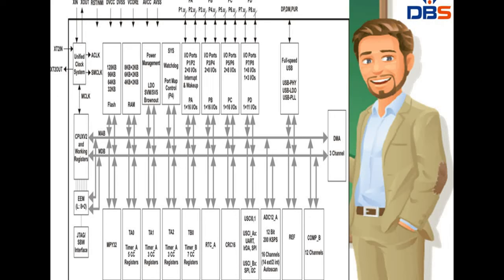Port 1 and port 2 have interrupt capability. Each interrupt IO line can be individually enabled or configured to provide an interrupt on a rising edge or falling edge of a signal. So here we are enabling an interrupt or configuring.